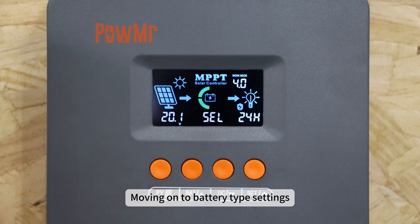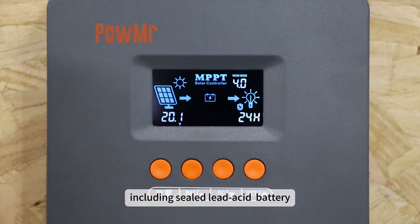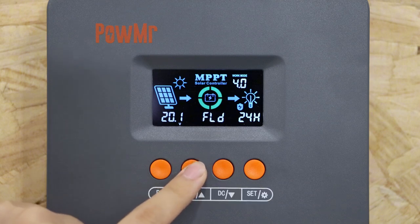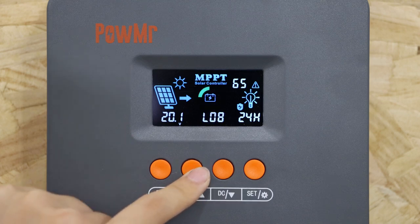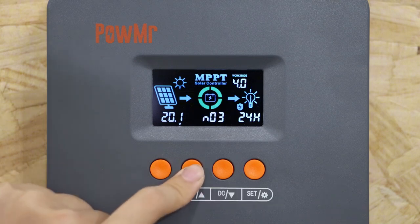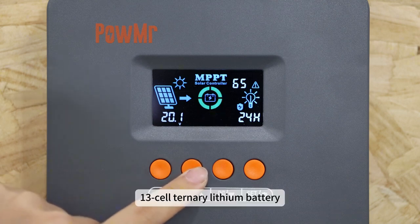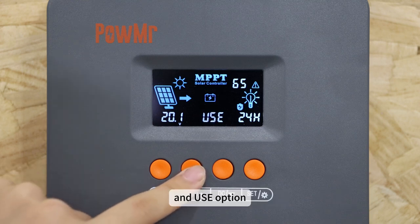Moving on to the battery type settings, the controller supports 40 predefined battery types, including solid-state battery, GEL battery, flooded lead-acid battery, 4-cell lithium iron phosphate battery, 7-cell lithium iron phosphate battery, 8-cell lithium iron phosphate battery, 15-cell lithium iron phosphate battery, 16-cell lithium iron phosphate battery, 3-cell ternary lithium battery, 6-cell ternary lithium battery, 7-cell ternary lithium battery, 13-cell ternary lithium battery, 14-cell ternary lithium battery, and the USB option.